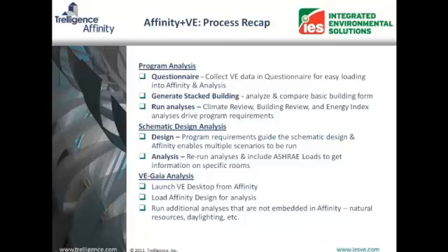We use the program requirements to guide our schematic design. And in the Affinity schematic design, we can run multiple scenarios of the building for comparison purposes to find the most optimal building form and adjust any project properties prior to moving into the detailed design. We can also rerun previous analyses like the ASHRAE loads, which gives us information on specific rooms. And finally, we can launch VE-Gaia directly from within Affinity for more detailed analysis like daylighting.